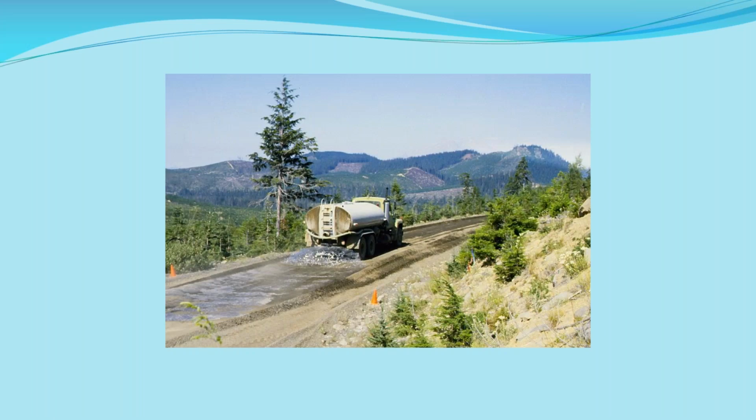This is a treatment that we had up in the northern Idaho area, with the Forest Service. This is a lignin sulfate application. You can see that they've cut the surface of the roadway and created berms on it because they had quite a bit of grade here, and they're really concerned about the material running off the side of the roadway. So they're trying to contain that lignin sulfate as they're applying it.